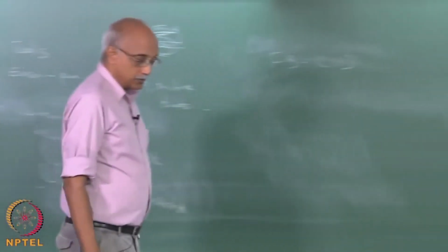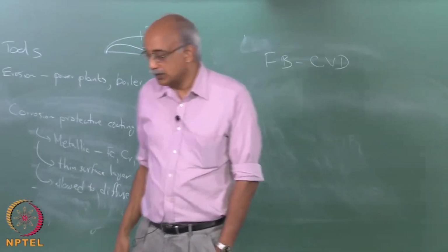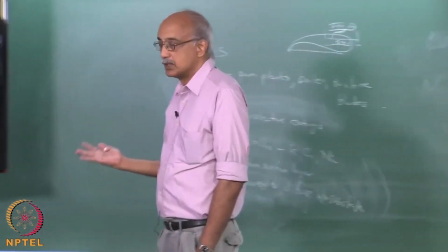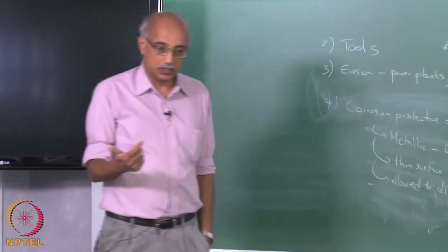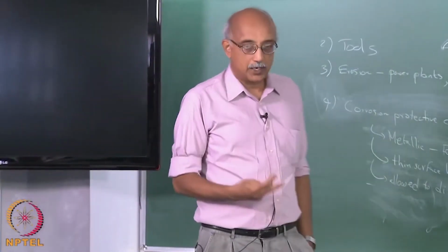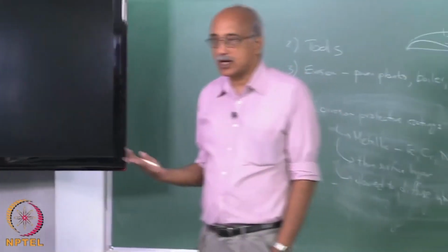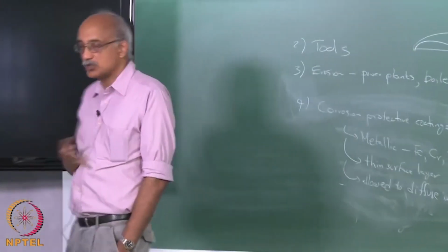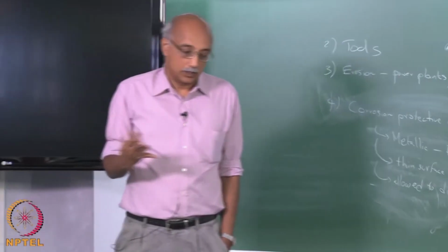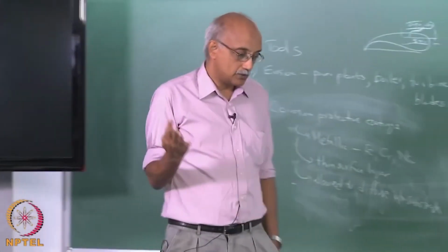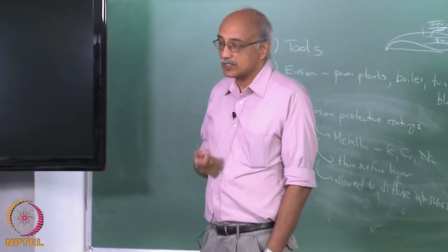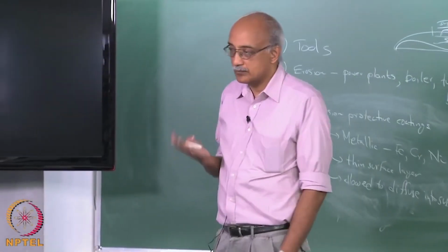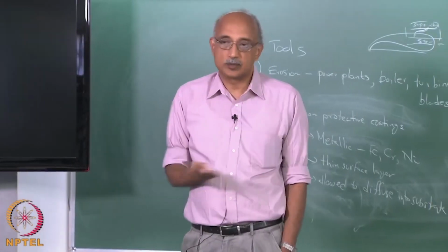Another application of CVD coatings is on top of polymers. There are frequently applications where the substrate has to be a polymer, but the surface has to have enhanced properties beyond what a polymer can give. Typically these are used in biomedical type of medical devices, especially medical inserts that go into the human body.